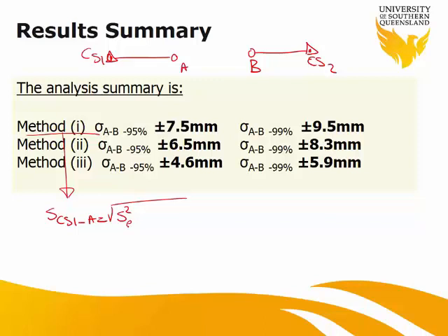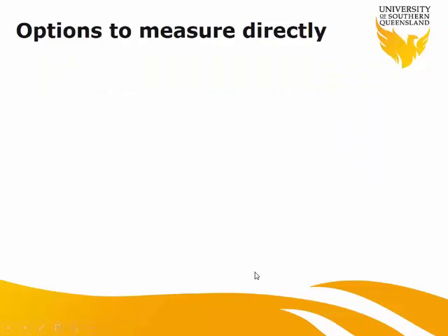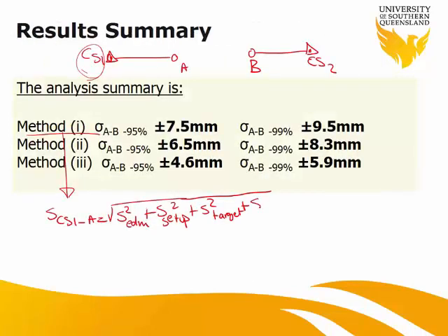So there's always an ADM uncertainty with measuring the distance. We have the setup uncertainty for our instrument. Good. And then we have the setup uncertainty for the target. And then we have another uncertainty, which is that we're not sure whether this control station position is 100%. There's no 100% confidence level. So there should be some error associated with that control station itself.